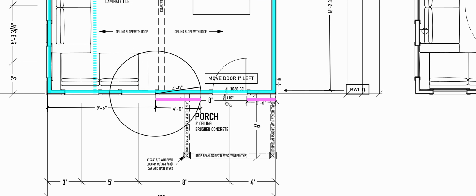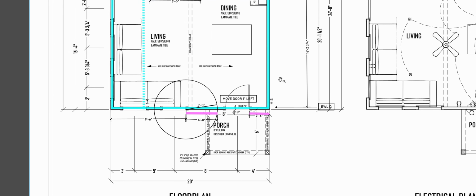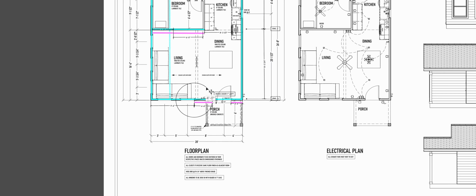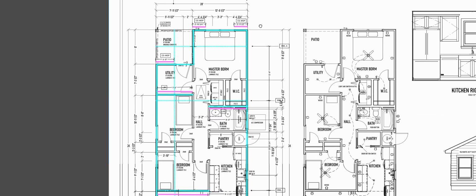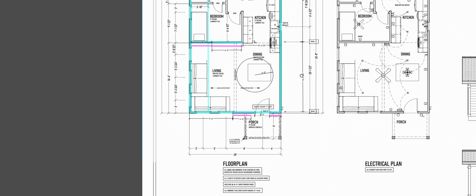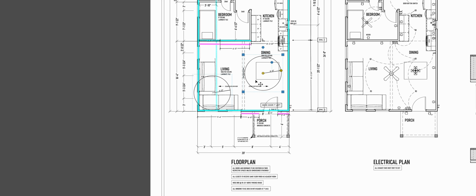Okay, and they're definitely less than 20 feet apart. Cool. Top to bottom is taken care of. So let's talk about the wind blowing from the front or the back. We got brace wall lines 1 and 2. These are going to be much easier because we got nothing but a wall.